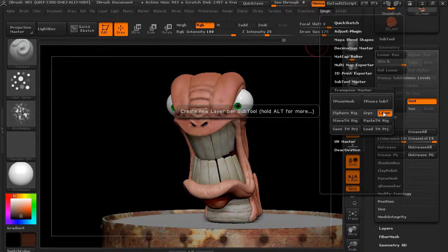That'll create layers that will contain the new sculpted detail that we're going to create. That means you can turn it back off if you need to. We can preserve existing polygroups. And now there's two buttons up here. We want to hit the one on the left. We want to create a low-res mesh for working with transpose. So we'll go ahead and hit that button.